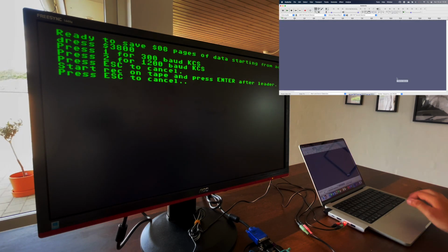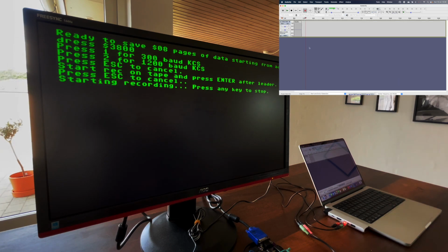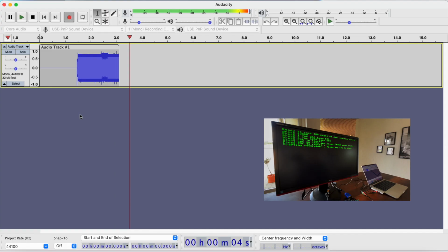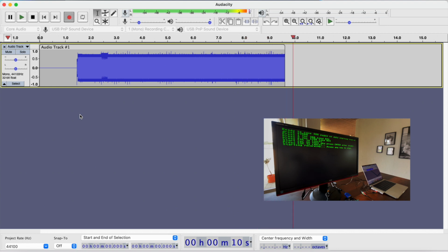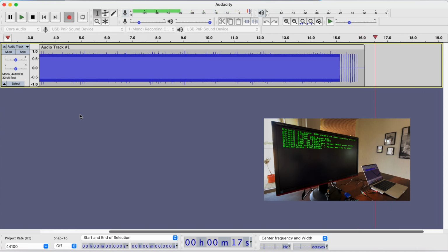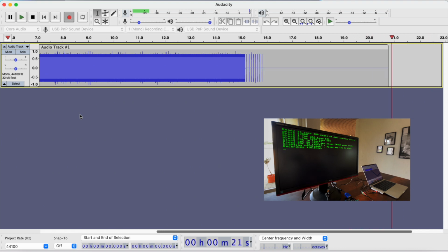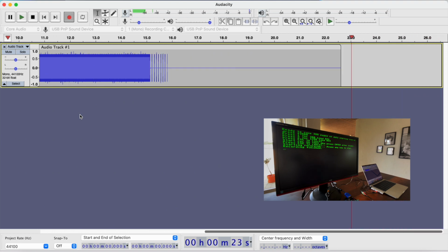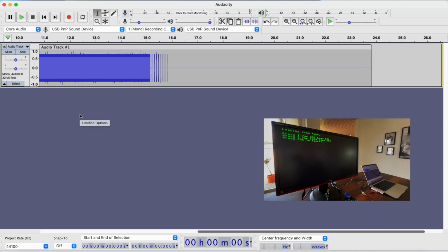I'm using 1200 baud Kansas City standard here, which is actually a bit misleading as the highest speed mentioned by Lancaster in the articles mentioned earlier was 600 baud by doubling the frequencies. Instead, I keep the frequencies the same and use 2 cycles of 2400 Hz for a 1 and 1 cycle of 1200 Hz for a 0. This is more like the BBC Micro, except I haven't implemented the error correction for that interface either.